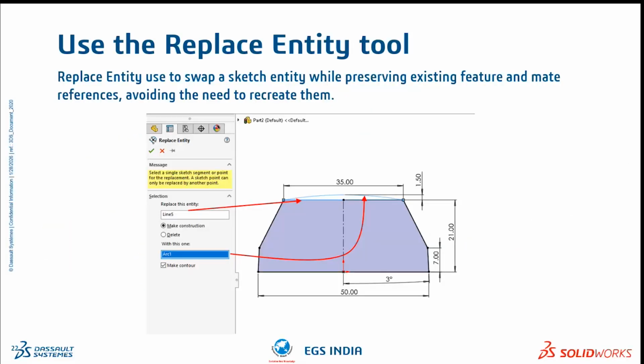Then the use of Replace Entities here. If any design changes in sketch or geometry are needed, normally we delete sketch entities and create a new one. But all the references get lost, and we must redefine them. This takes extra time and can create errors.